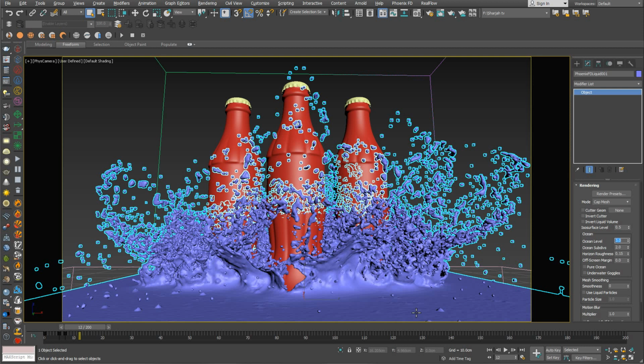Now I have these small artifacts, some drops coming down, and sometimes it's just random because the mesh needs to be smooth again. So I can introduce some smoothness, 1, and that's good. I reduce this, and I also always tend to activate use liquid particle, which can smooth the mesh more, and it will take care of the ends. So now I have something decent.